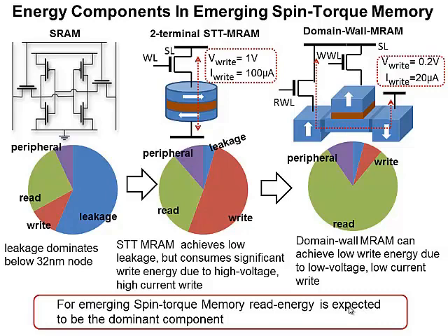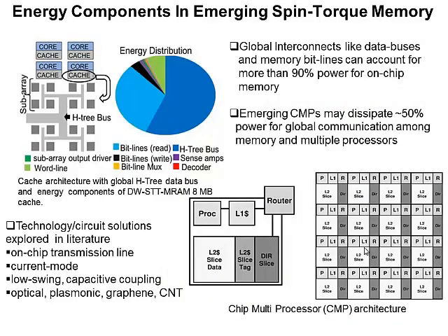So now, if we look at the most probable scenario for MRAM, this is going to be the energy division for the MRAM technology. Most of the energy is going to be dissipated in read and sensing operations, which also includes the data transport. Here, the energy dissipation for a two-level cache with MRAM has been shown. It shows that the two most predominant energy components are the one due to charging and discharging of the metal bit lines for sensing operation, and the other is for data access through the H-tree data bus.